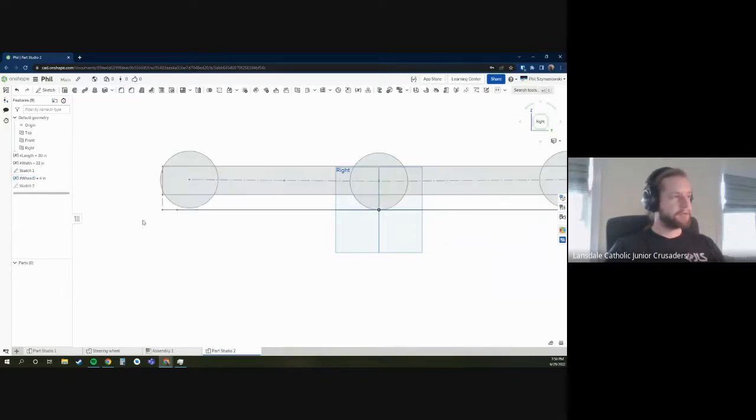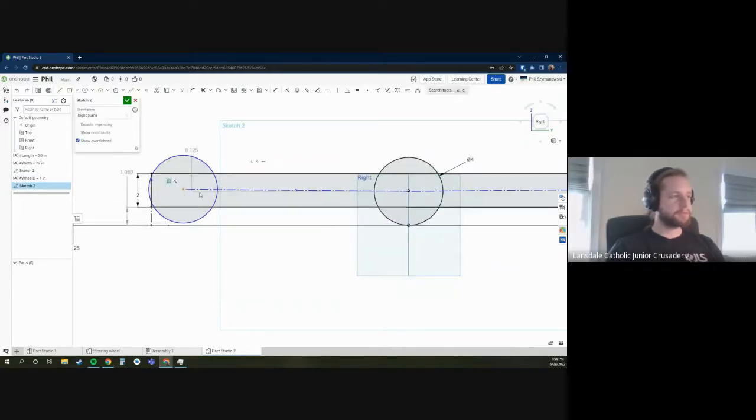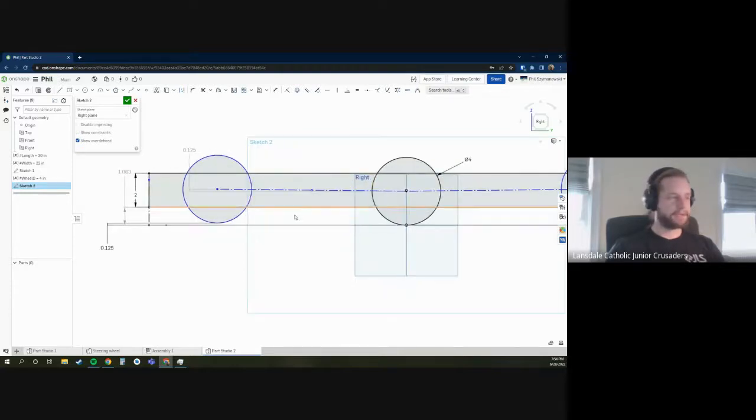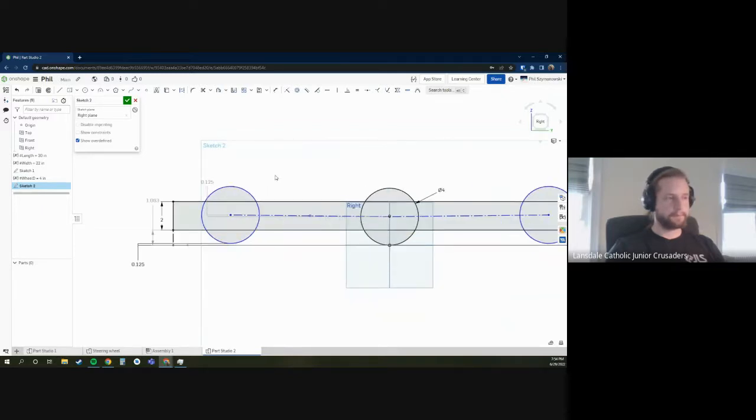Well, now that we created this variable, we can go in there and instantaneously change the 4-inch wheels, and it automatically updates this whole sketch for us because of the way that we constrained the circle to the point, the way that we constrained the tubing to the center line between these two, so on and so forth. It kind of does all the math and all the tricky stuff for us. Does anybody have any questions yet?